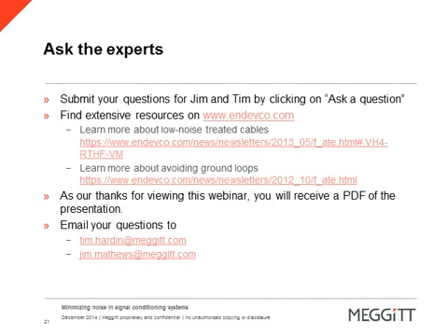Our next question: we typically use 320C03 piezoelectric accelerometers with an isolated mounting stud and Meggitt 2775B signal conditioners set up in ISO mode. However, sometimes for higher shock levels, we cannot use the isolation studs and must use a shock stud, a simple thread stud with no isolation. In this instance, what should be the ISO GND setting on our signal conditioner?